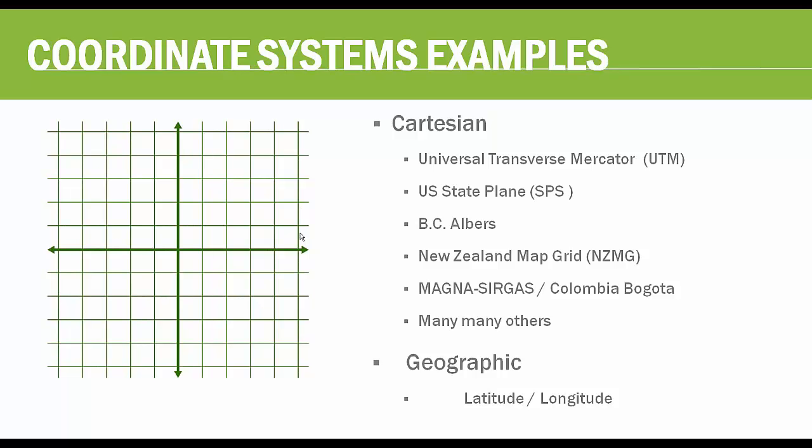So I'm sure everyone here is familiar with coordinate systems. If you're in the business of designing roads or sites, these will be familiar to you, but I thought I would just bring them up here as an introduction. Here are some of the common coordinate systems that we see, the top 3 in particular, and there's all sorts of coordinate systems that are available, and I'll explain how those work with RoadEng a little bit more, but there are many of them. The final one, geographic coordinate systems, you can actually work to a certain extent in terrain with lat-long coordinates, but it's not recommended. Things like calculating areas and distances don't work with lat-long coordinates, so we tend to discourage that coordinate system.